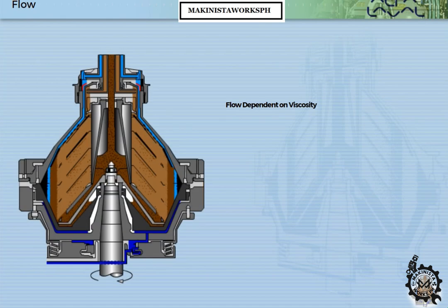The separator has a limit to the flow rate it can handle, above which point it will be unable to swallow what is being fed. The amount of liquid it can swallow also depends on the viscosity of the liquid, since this determines how it passes across the disc stack. With no change in viscosity, an increase in flow will result in more oil passing across the disc stack. This will move the interface outwards. For a decrease in flow, the interface will move inwards.